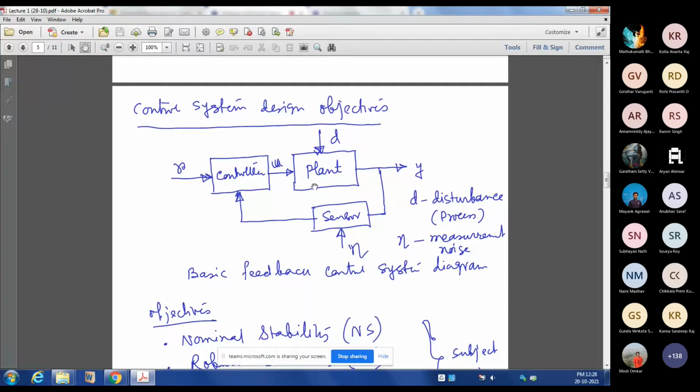So for controller design, what do you do? The actuator and plant transfer functions we multiply, and then we consider the whole as a plant. And sensor dynamics, remember, we normally do not consider. The gain part we consider, but the dynamics part we do not consider for controller design in general, because sensor dynamics is much faster than your plant and actuator dynamics.